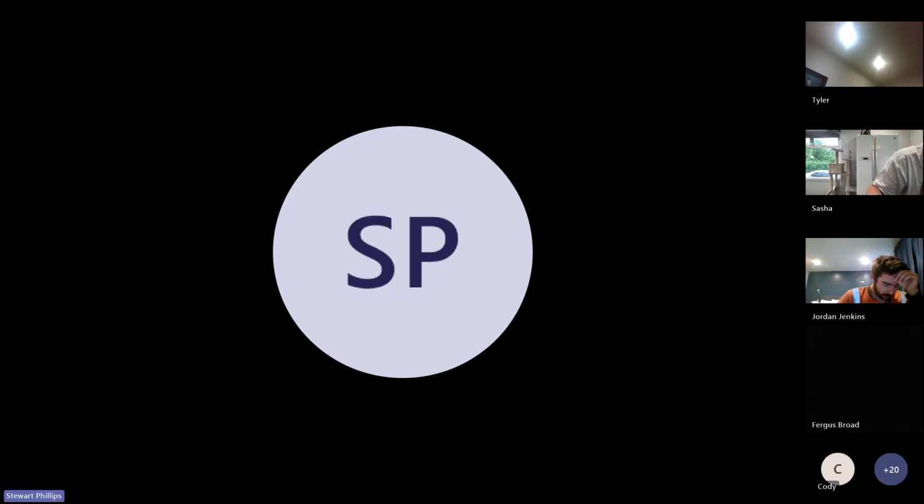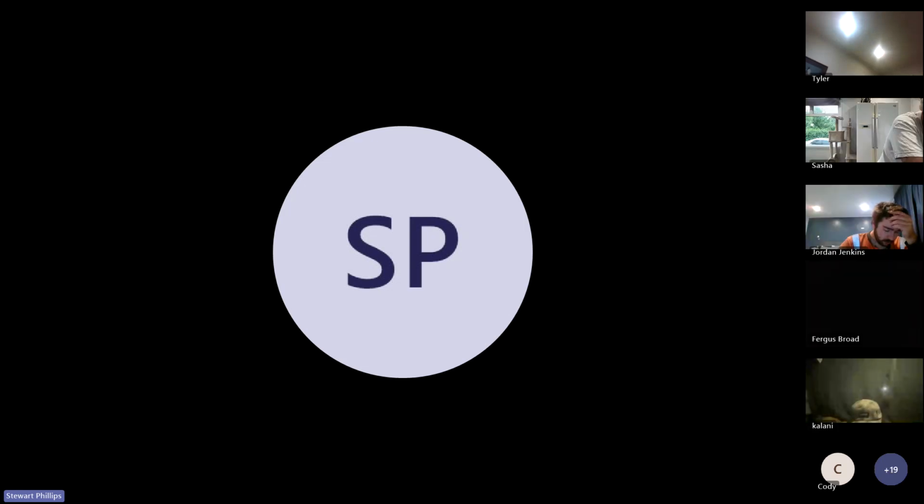Yeah, so you guys are on the right track. The answer is arc quenching. The fuse contains materials like quartz sand to absorb and extinguish the arc safely. The quartz sand mixes with the vaporized silver, I can't remember off the top of my head, and mixes with the sand, which quenches the arc immediately.